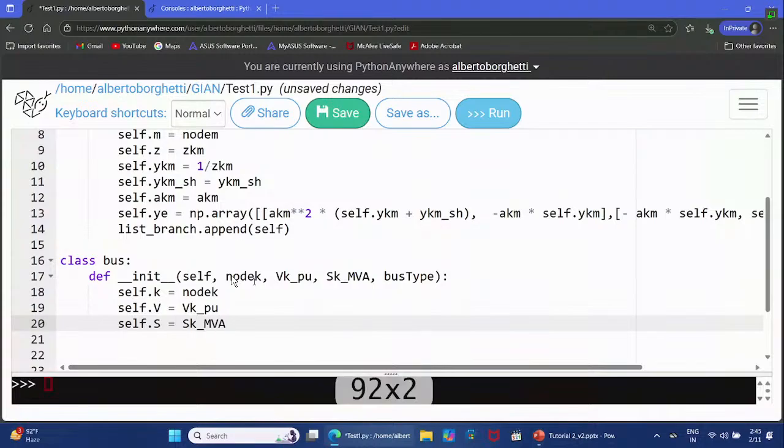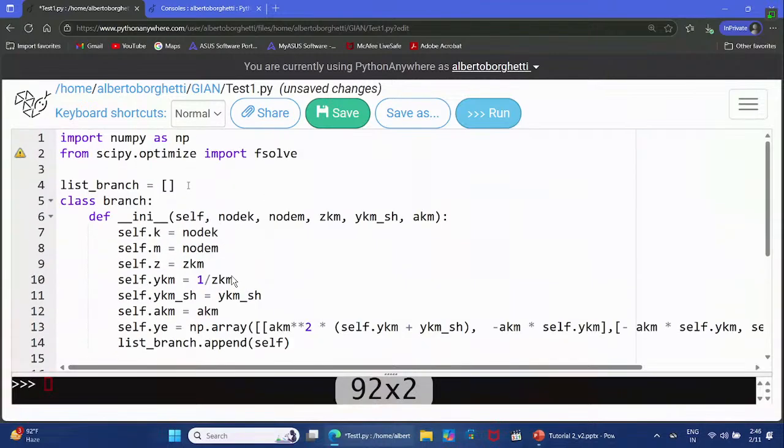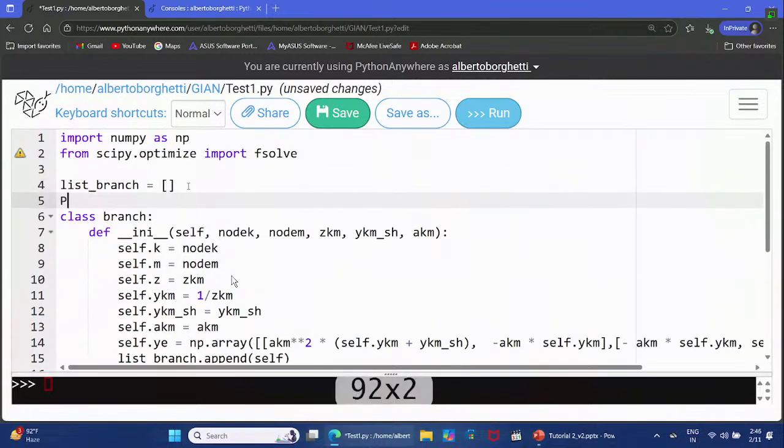But since we have started to use the per unit, we can also put the power in per unit, so I can divide it by P base, the base power for the per unit system. In this case we need to define P base before, so we can take, for example, a value that is in accordance with our calculation, for example 100 or something different. We will see.